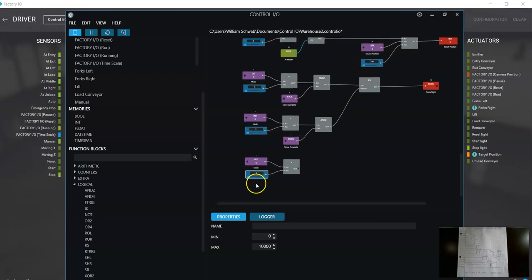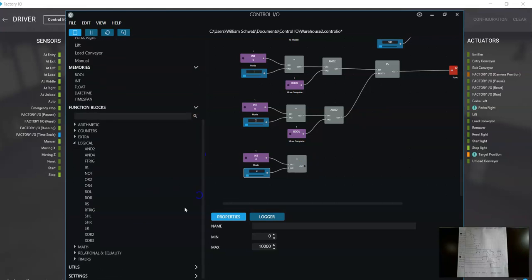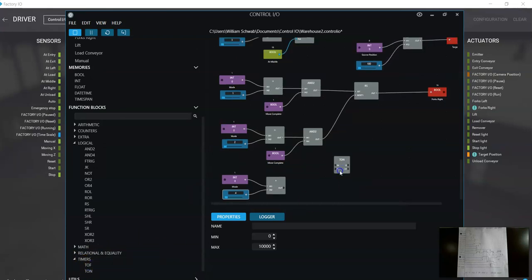on the timing diagram, but we actually do count to 4 when we move home. We're moving home on count 3. When it gets to the home position, it goes to count 4. Now again, what I had to do to make it work was go in here and put in a timer that gave it a little delay here.